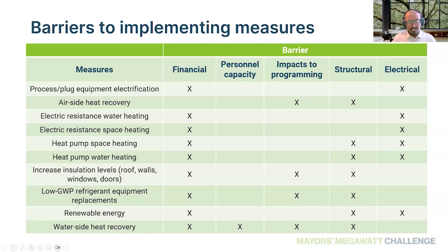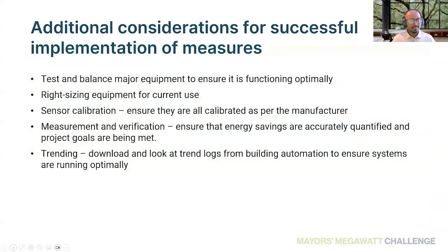And like Sean mentions, I say a lot, it really depends. So additional considerations: testing and balancing for major equipment. This is going to be just critical, like I mentioned earlier, on the phases to make sure that you are operating the best way you can, so you can have a lifetime of great operation, not just an idea of how it should operate on paper somewhere, and then not actually doing that for the next 20 years of operation. Right sizing equipment, so you're not having systems that are operating at part load a bunch of times and just not using the full capacity, losing a lot of efficiency through these things.